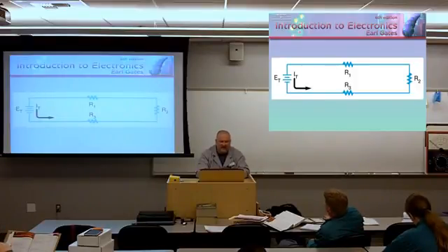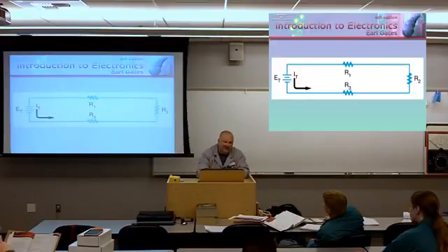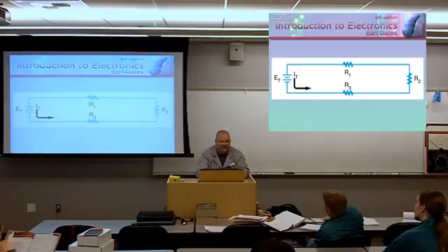Voltage divider. In this particular circuit, I look at it, and yeah, I've been doing this since puberty, but I look at this, and what do I see? I see a voltage source and 3 voltage drops. Voltage rise and 3 voltage drops. 3 loads. I don't know what they are, but I know these loads are connected in series. And I know that all the current that flows out of the negative terminal of my voltage source has to travel this complete path. No place else for it to go.